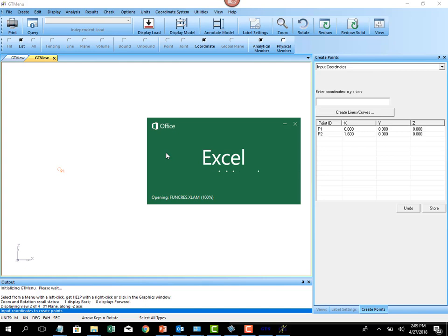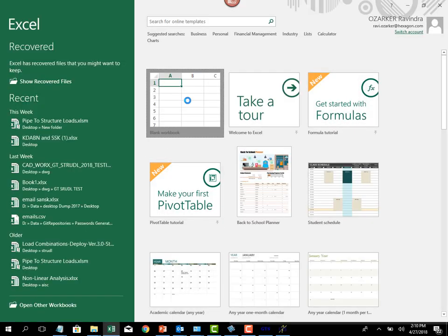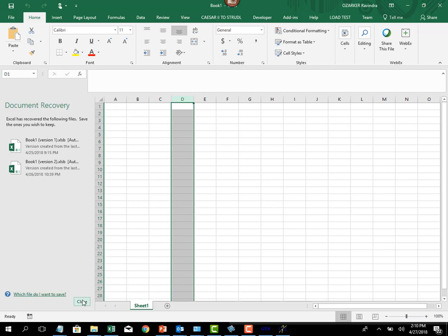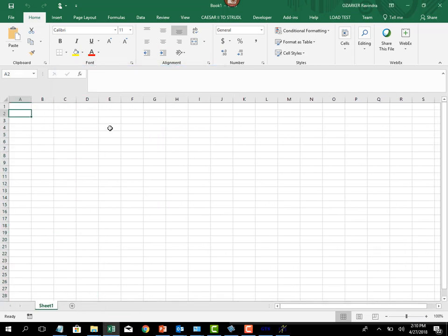Okay, so I'm just going to open up Microsoft Excel and just type in the grid spacings, and you can go in and add those up to convert them to actual node coordinates. So here I am, I'm just going to say, okay, the first one is at 0, like we typed it in. Okay, then we have one at 1.6, then we have one at 0.8, then we have 0.4,